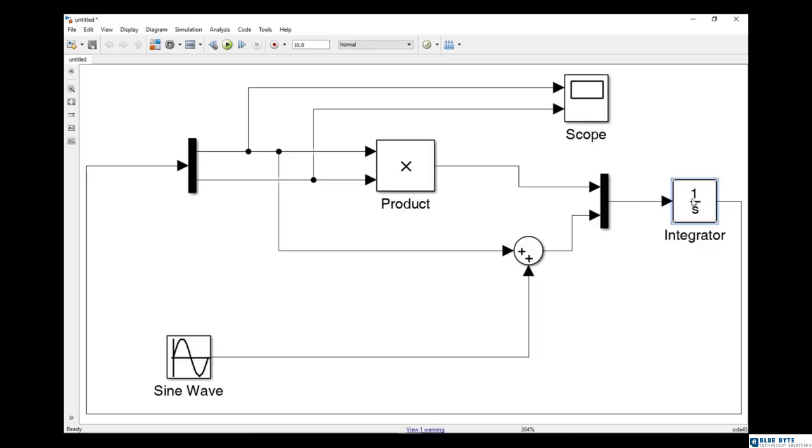In the next chapter, I will talk about MATLAB and Simulink errors more. But in fact, in simulation, you may face a lot of errors. In this regard, there are many reasons. One was the error we had here. The other may be related to the amount. For example, you give an amount to a specific block and you specify that number with A. Then after running the simulation, you may face an error because A is an unknown amount. I will try to talk about errors later, but generally Simulink itself explains why you have these errors.